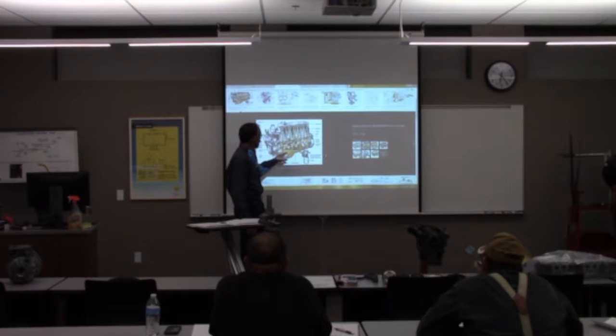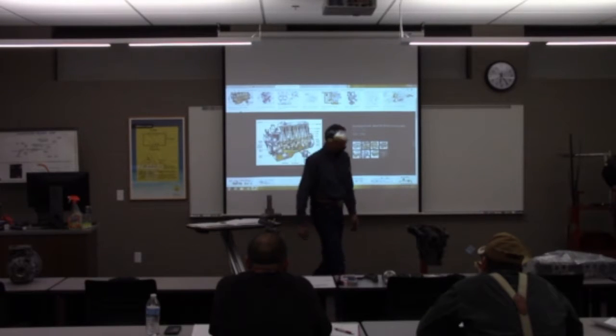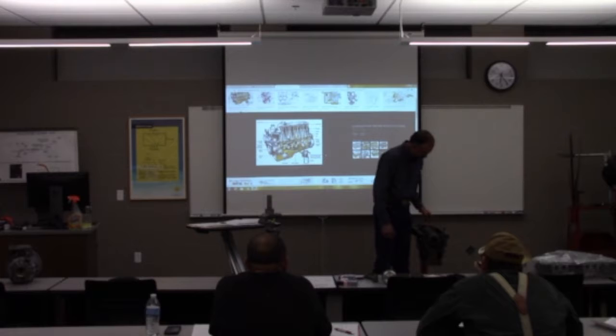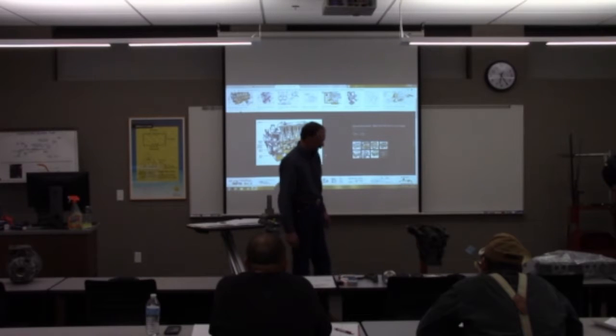A lot of the oil passages will be partially cast and partially drilled. You can see, for example, in this, there's an oil passage that goes the entire length of the block right here that's drilled, and after they drilled it, then the ends of it, and see it's drilled this way too, they plug the ends of it, but there's a lot of places there that can trap debris too.